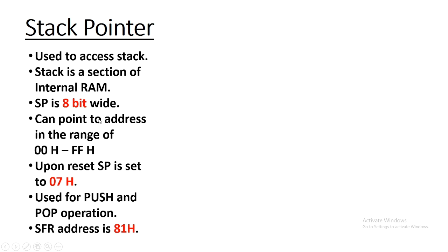So this register is an 8-bit register. This register is used to access the stack. The stack pointer in 8051 can store a value in the range of 00 to FFH. So it can point to any address in this range.